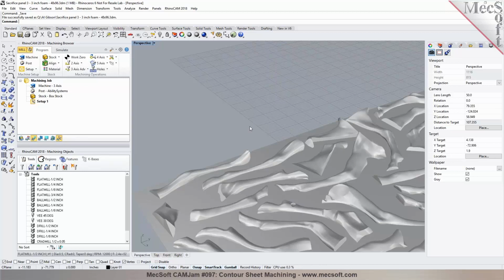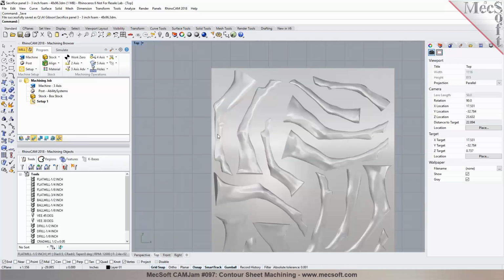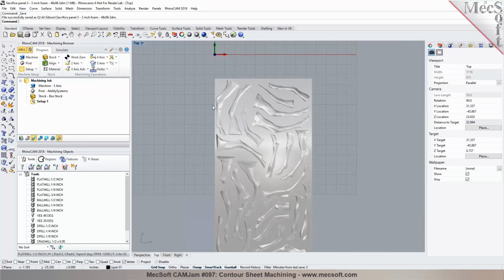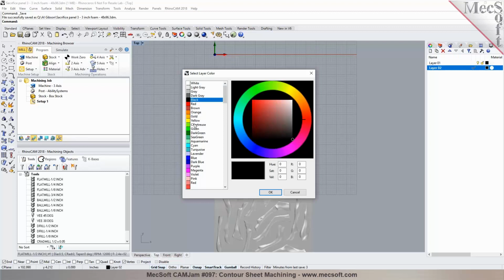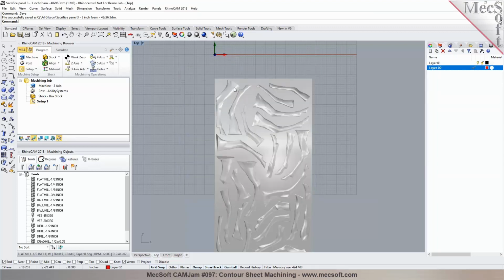We don't want to cut the whole sheet if we don't have to. Okay. All right. We can certainly help you with that. So, the benefit of working in Rhino gives you a lot of different tools in the CAD itself. So one of the ways I would probably recommend is I'm going to go into those layers in Rhino and insert a new layer. And I can pick a different color for the layer if I'd like to. So I can say I want to specify a different color. I'll just pick a red for now.